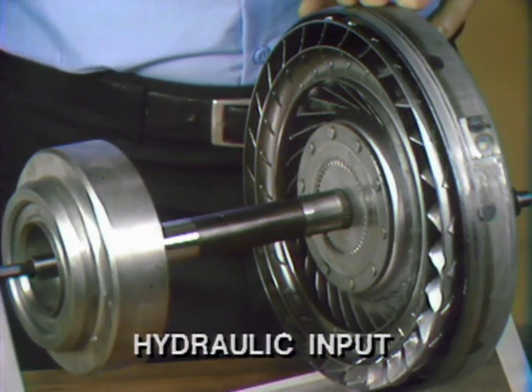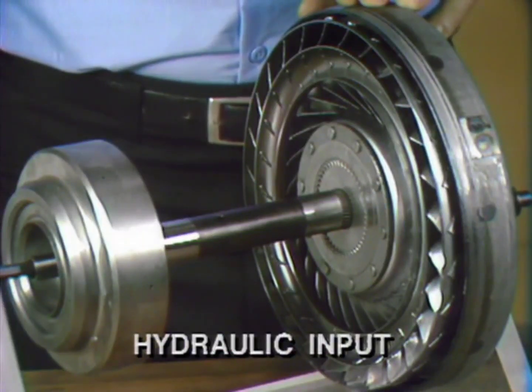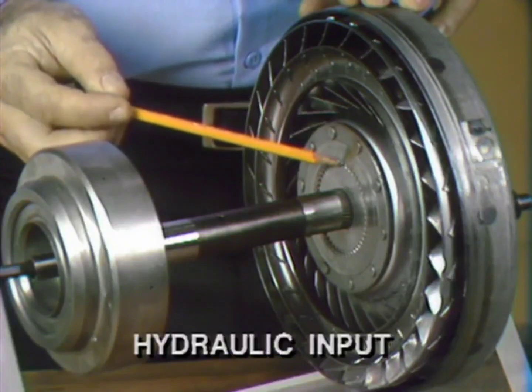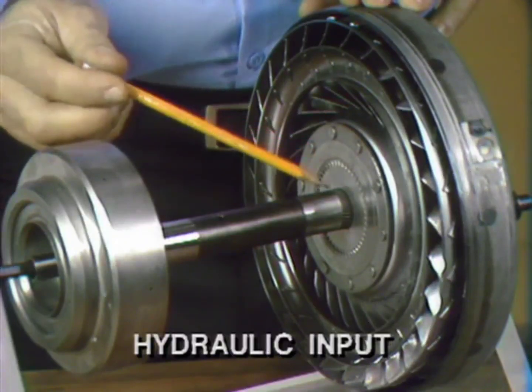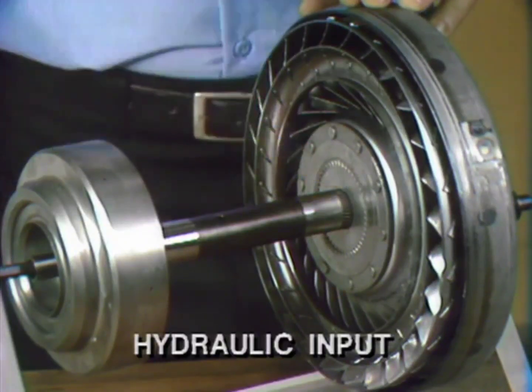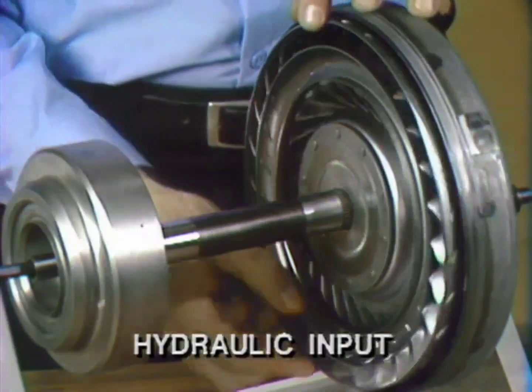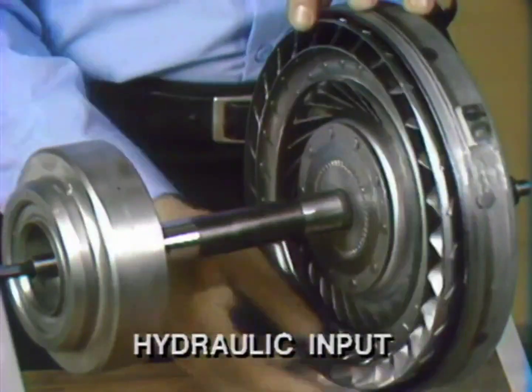Hydraulic input can happen two ways: all hydraulic, or in split torque, hydraulic and mechanical. This is because the sun gear for the splitter planetary unit is splined into the hub of the turbine, and the turbine shaft is splined into the sun gear. With the turbine and shaft in place, we can see what happens in 100% hydraulic input.